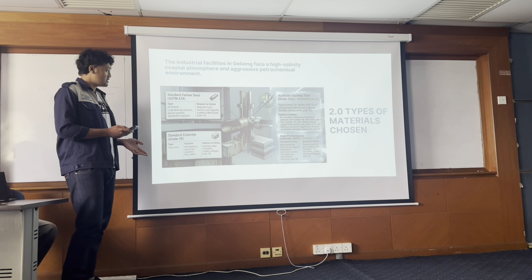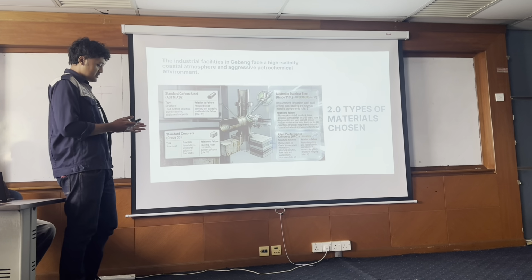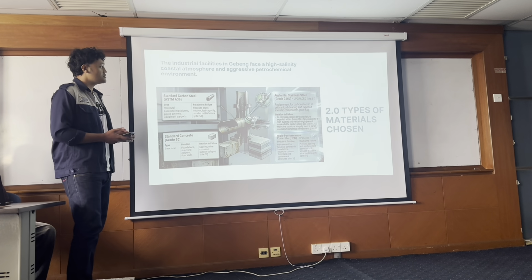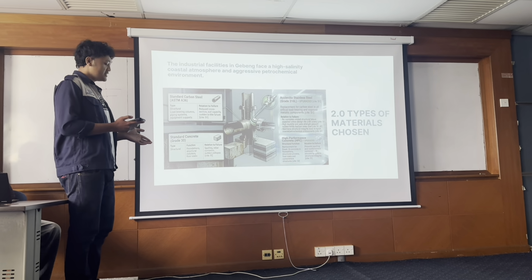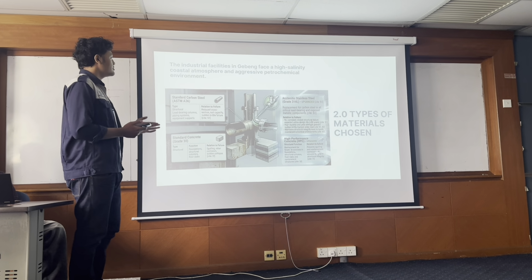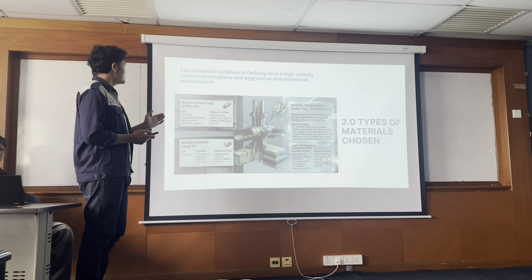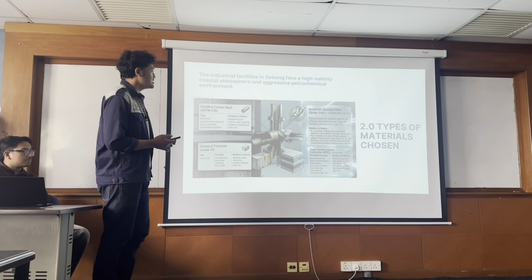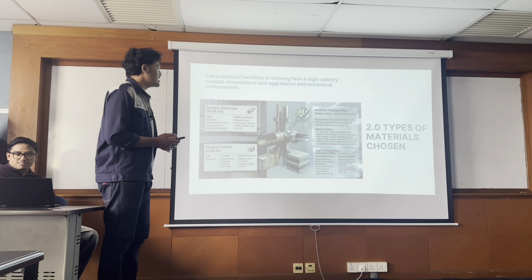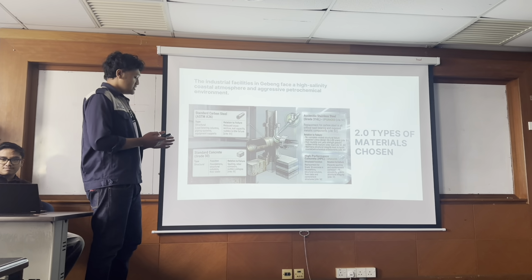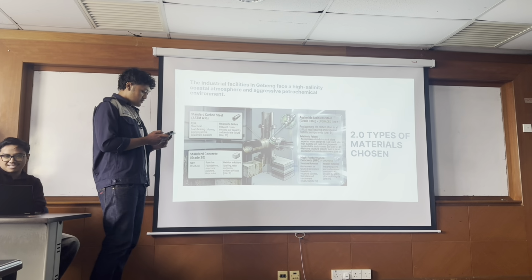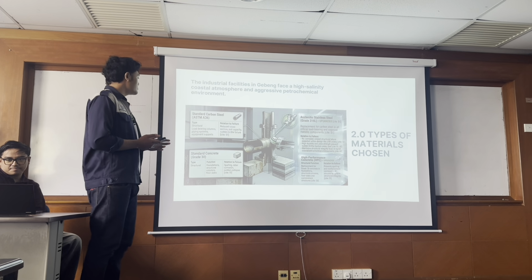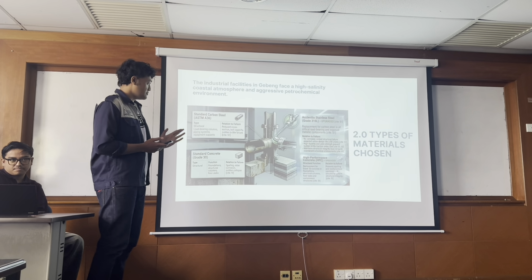So the upgraded material, to ensure that the material can last a very long time, we have moved from the standard carbon steel to the austenitic stainless steel, which is 316L grade, for all critical components such as piping system, equipment support, and also load bearing column.